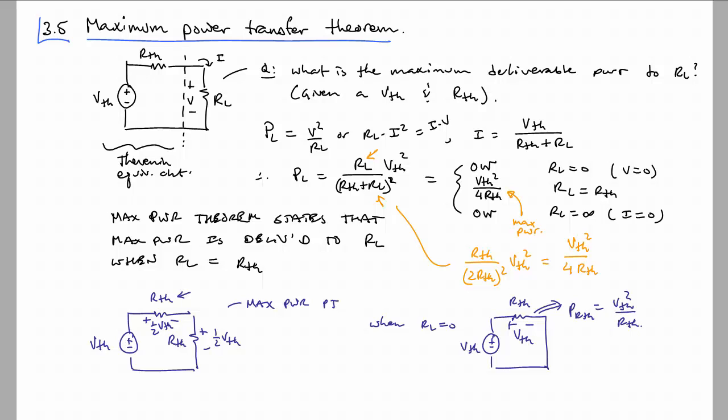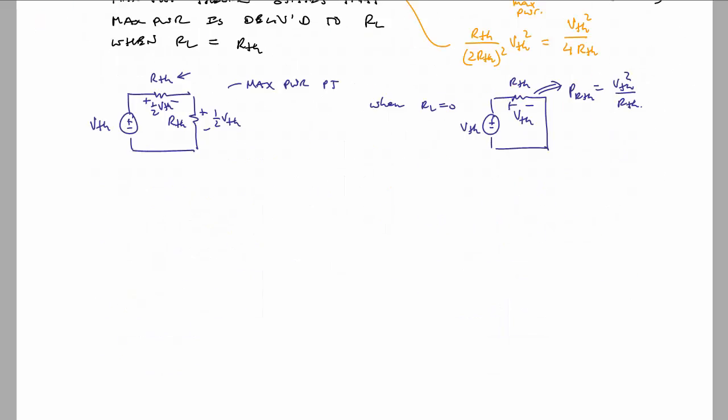So one thing to remember is that when we talk about maximum power transfer, we can't forget that this is in the context of a fundamentally lossy proposition. It makes sense when there is a source that has a source resistance. In other words, if you have, say, a battery that has a Thevenin resistance of 1 ohm, the most power you will ever get from that source will be when your load is 1 ohm. If you decrease or increase the resistance on either side of 1 ohm, you will find that the power decreases.